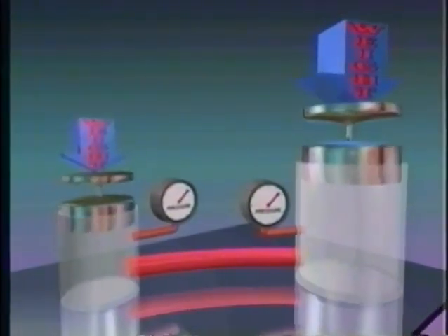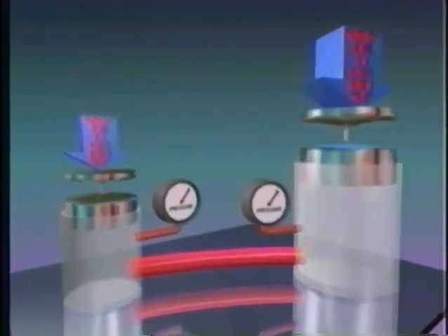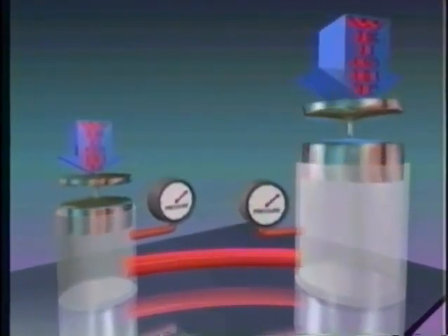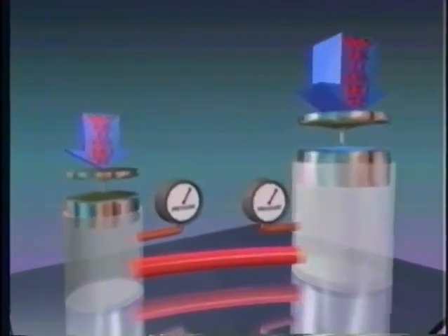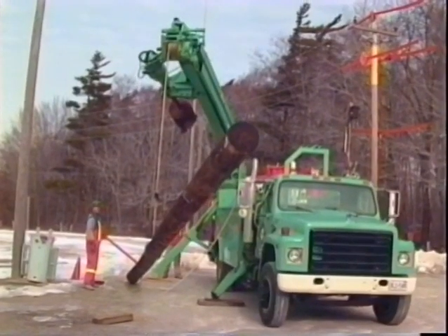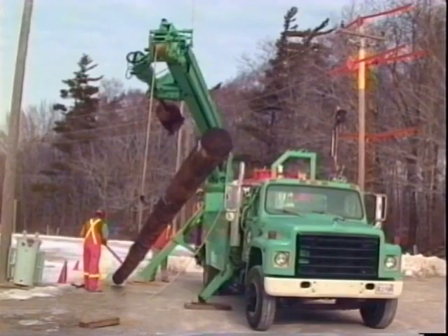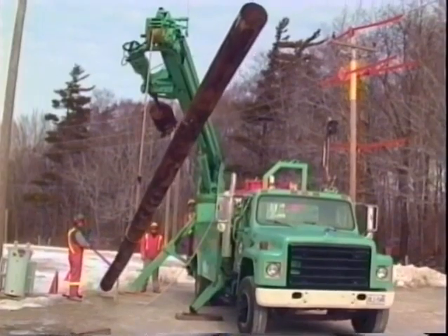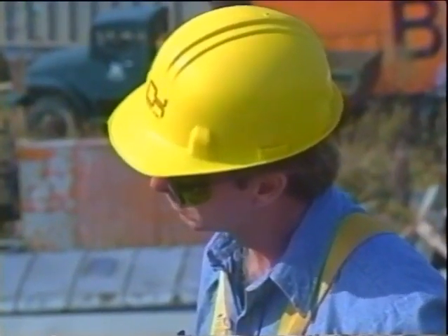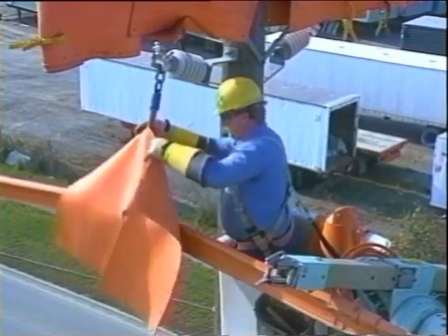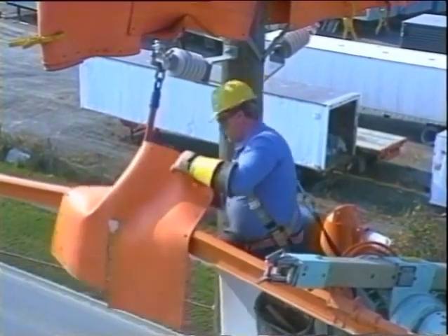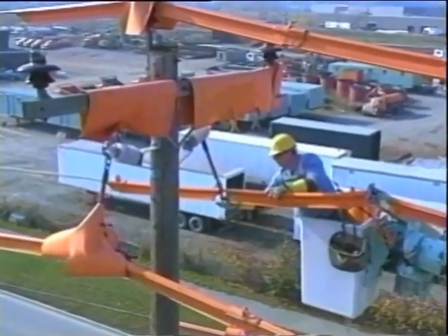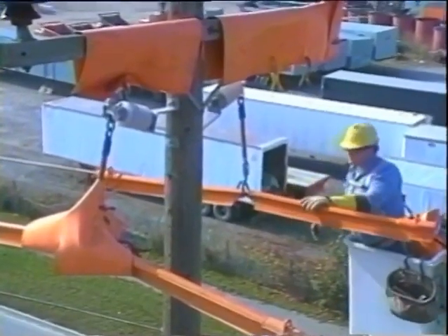Going back to the two-piston setup, keep in mind that the connection between the pistons does not have to be rigid. In utility work, for instance, most hydraulic hoses are made of neoprene. What this means is that a relatively small stationary power supply can deliver large amounts of power to moving components. And there is one other advantage of hydraulic power transmission that makes it especially attractive from a utility standpoint. If the materials used meet the appropriate standards, the hoses and hydraulic fluid are non-conductive.